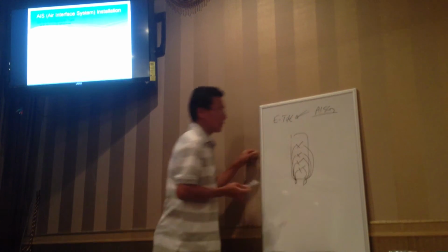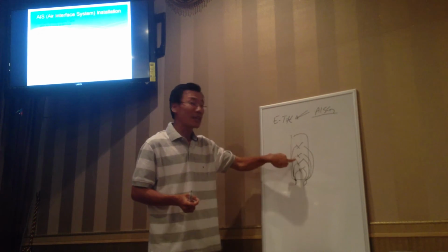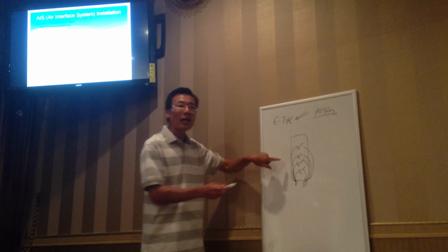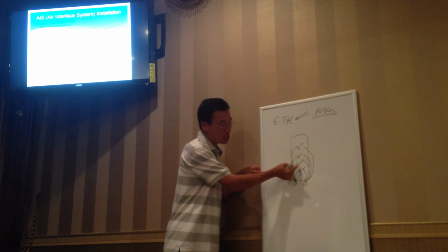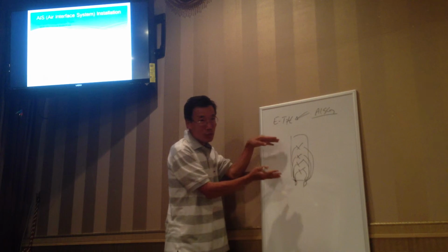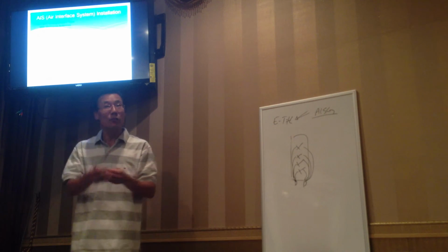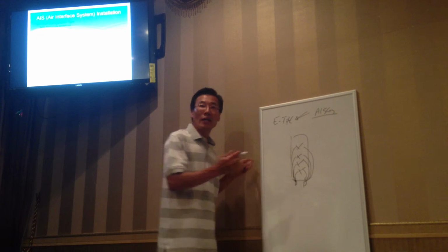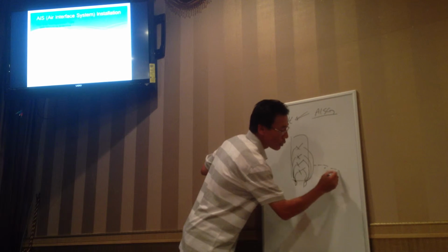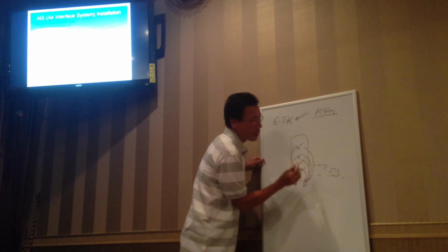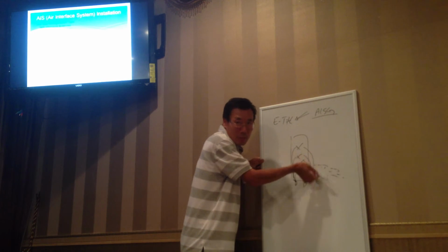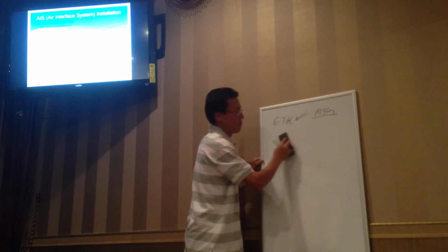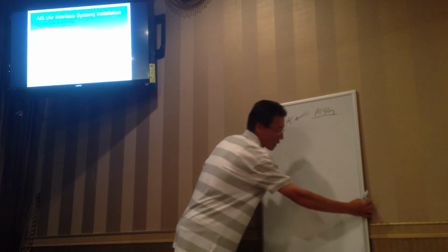So when delivering the signal to each radiator, right? There's a time delay here. Even though short cable, long cable, small lengths of cable, there will be delay. So controlling this delay, right? Control this delay, now they can adjust this beam up and down. Okay, that's beam steering. I'm sorry, that's electrical down tilt.